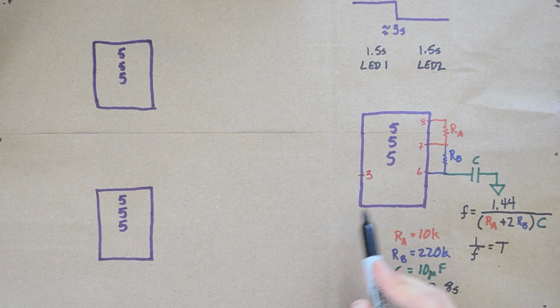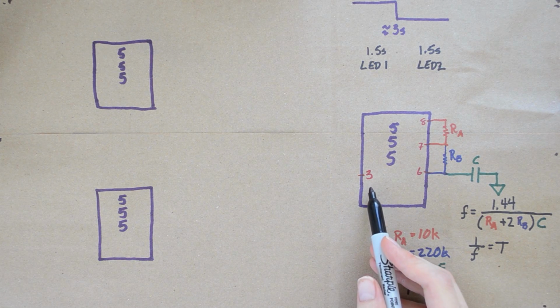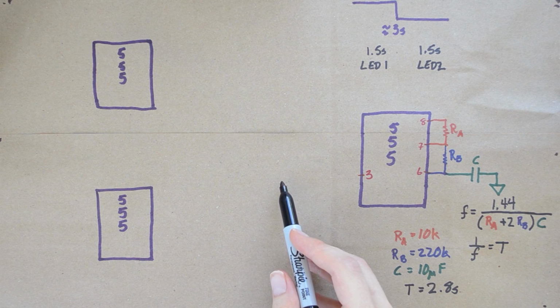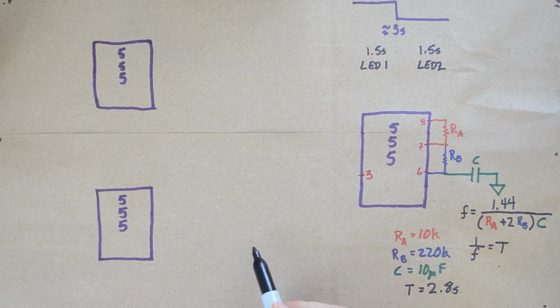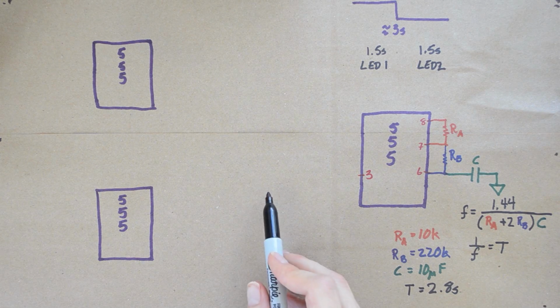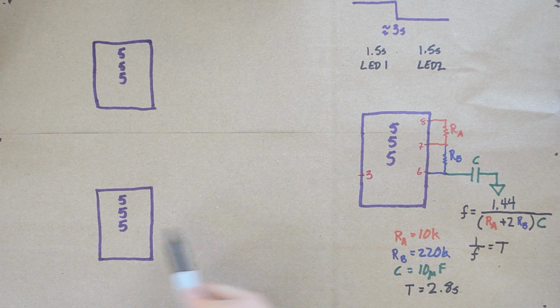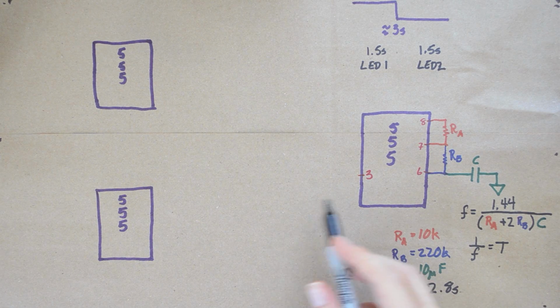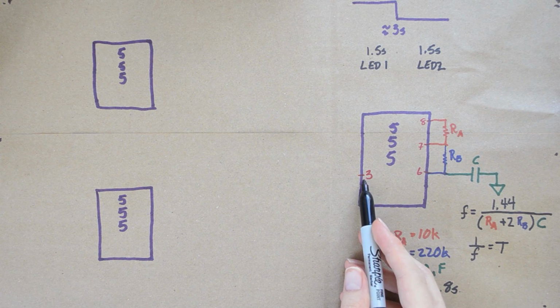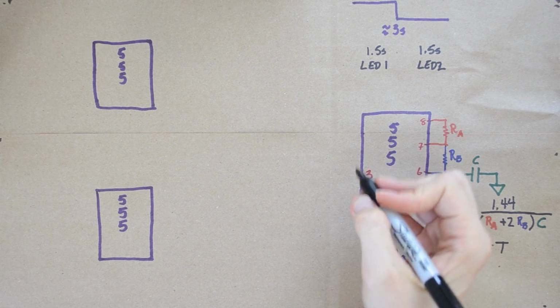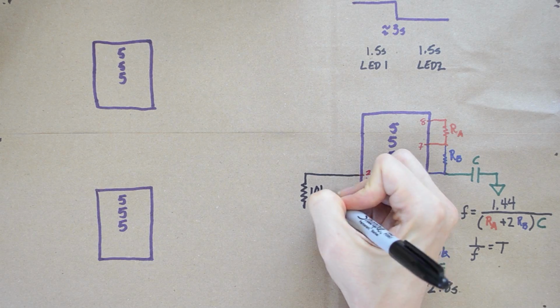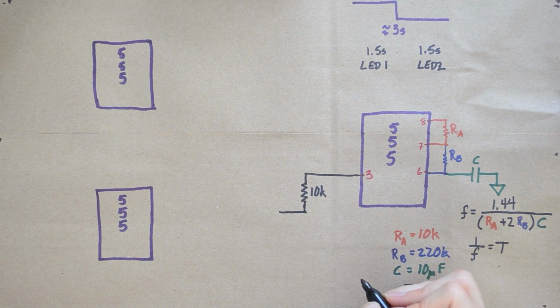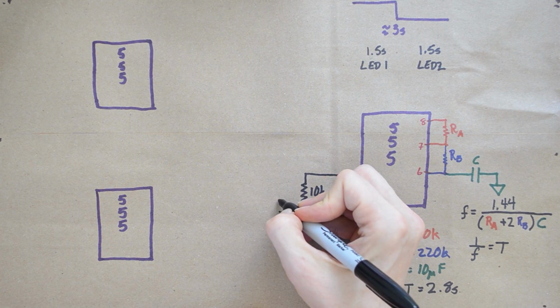Now, I showed you in a previous video where you could do this with an LED. You take a transistor, put it on this pin, you turn that transistor on, it acts like a gateway, and then it powers up LEDs. Well, in this case, we're going to have that transistor power on this 555 timer. Whenever this output is sourcing voltage, we're going to come out, go to a resistor, and have this at 10K. This resistor is then going to feed into an NPN transistor.